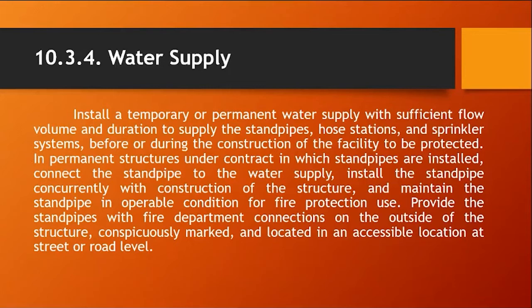Provide the standpipes with fire department connections on the outside of the structure, conspicuously marked, and located in an accessible location at street or road level. So, these are the standing metal pipes we see in areas, usually near buildings.